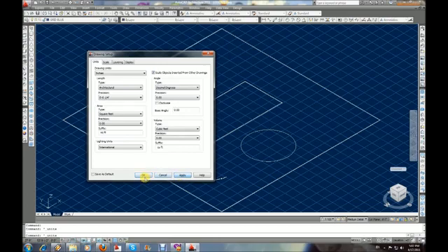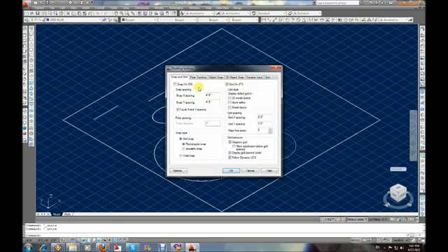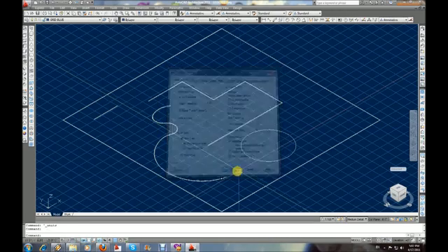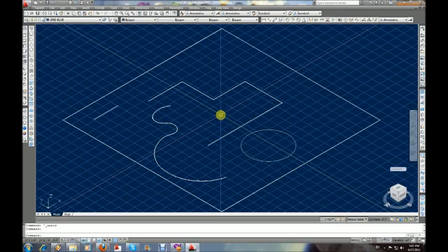For this tutorial I have set my units by going to Format, Units, clicking on Drawing Units, Inches, Architectural, Apply, and OK. Also, I have put my grid display settings to snap for 4 feet by 4 feet and grid spacing 2 feet by 2 feet. That kind of gives me how the things look like here, and you can set your settings to whatever you prefer.